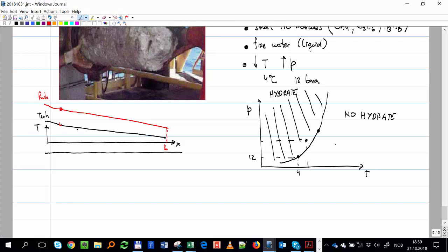If you plot now every pair of points, for each position, every pressure and temperature, you plot it in this diagram, it's going to show something like that. Let me use another color. That will be P into the flow line, and it will go out like that. P out and T out, where both pressure and temperatures are reduced along the flow line, as I'm flowing.